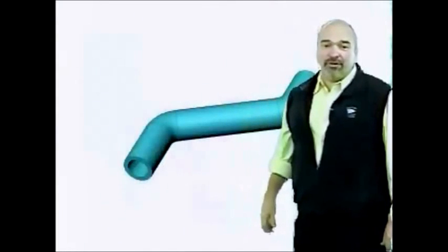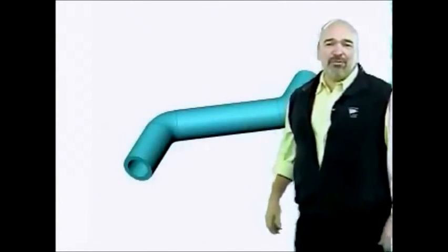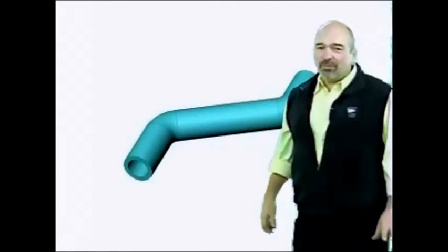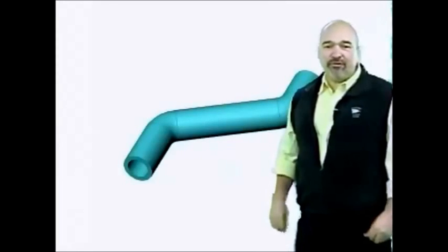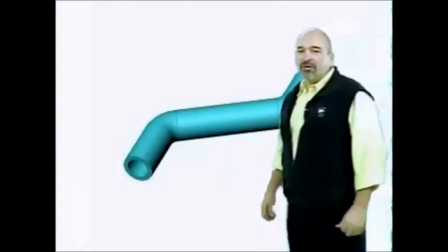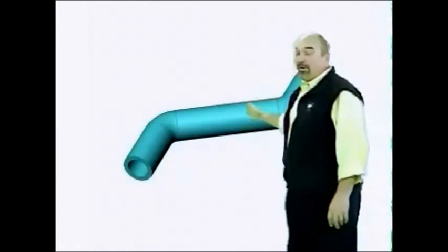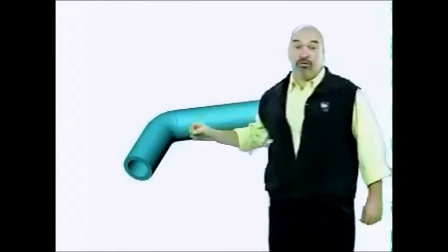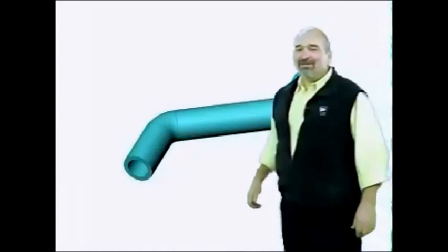Don't be surprised if you don't find your parts in the Y14.5 standard. The standard is a collection of building blocks. There are an infinite number of ways to combine these building blocks to control your parts and still be in compliance with the standard. The standard does not, for example, specifically show how to tolerate such parts as preformed hoses, tubes, and bent rods. However, the building blocks for controlling this sort of part are found in the standard.